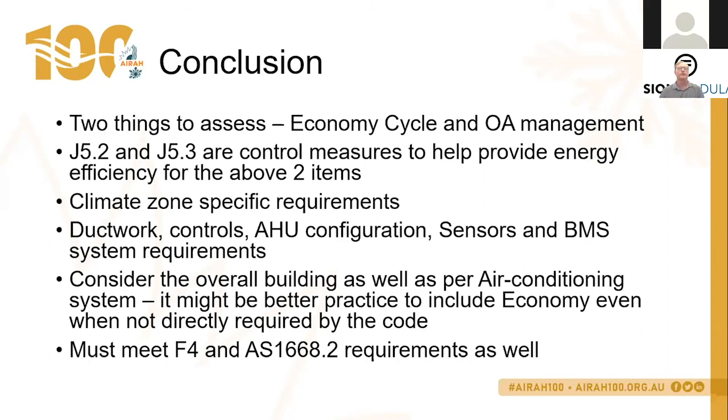If you don't have exhaust from the space, then you don't have an energy recovery ventilator because you don't have the exhaust air to use to energy recover from. So no, you then do not need to comply with that clause.